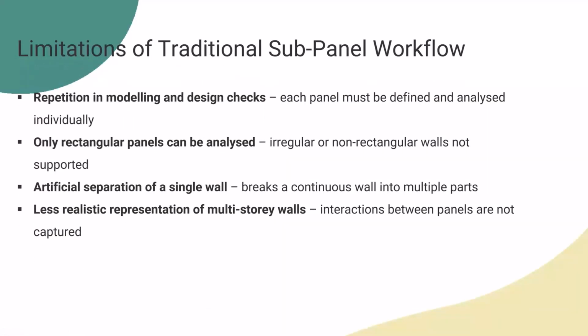This slide summarizes the main limitations of the traditional subpanel workflow. First, there is a repetition in modeling and design checks. Each wall panel has to be defined and analyzed individually, which takes time. Second, only rectangular panels can be analyzed, so more complex wall shapes couldn't be handled directly.